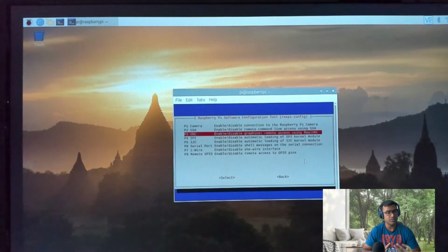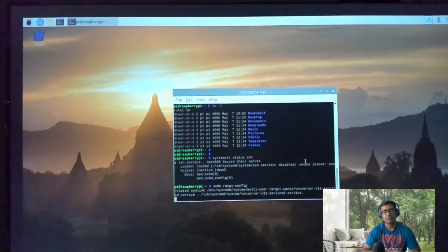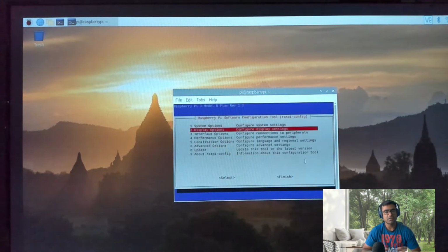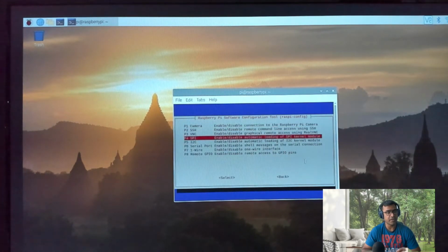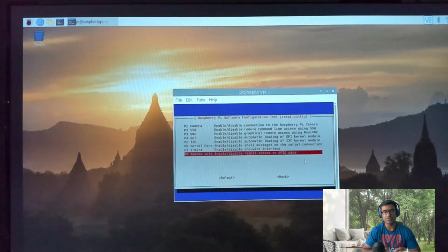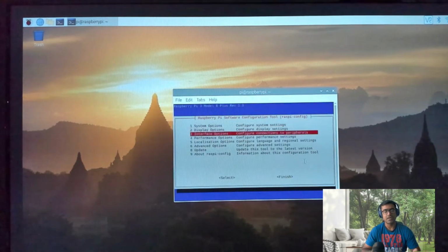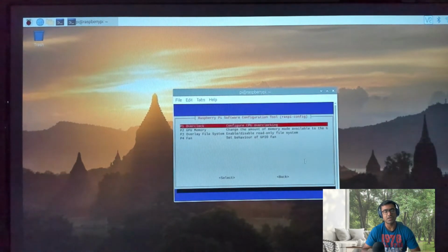Then we are planning to connect a camera, so let's enable camera GPIO, enable SPI GPIO, which is for sensors and other services. This is very important because you may start connecting your sensors and actuators on your GPIO, only to find that it's not working or the library is not available because these pins are disabled, and hence those capabilities are not available to you.